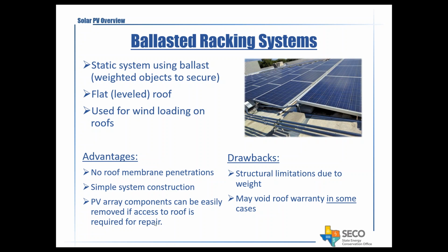Another thing to consider whenever installing solar PV on the roof is to look at the condition of the existing roof. If it's something that y'all plan to replace soon, then that may want to be done concurrently or before the PV system is installed. That just helps you avoid additional costs with having to move the system if it's installed before the roof work is done.